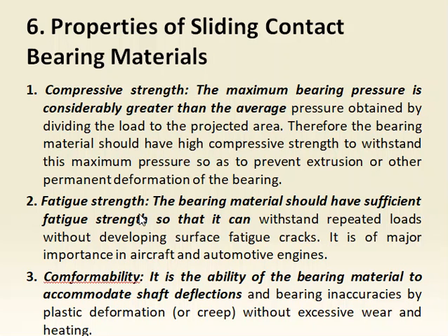And the next important one, conformability. It is the ability of the material to accommodate sharp deflections and bearing inaccuracies by plastic deformation. That means creep without any excessive wear and tear and heating. So that is the most important aspect of conformability.